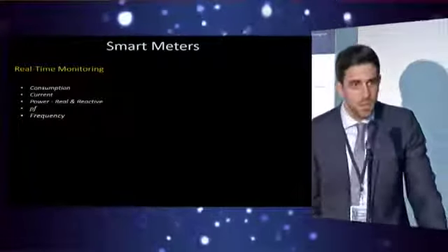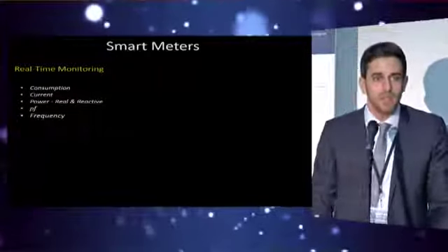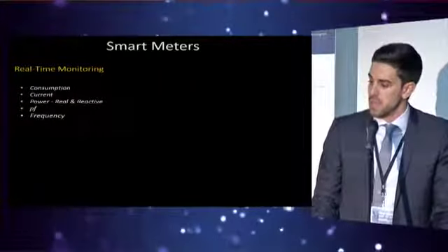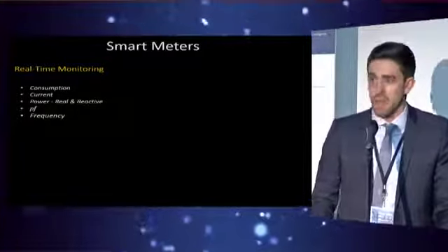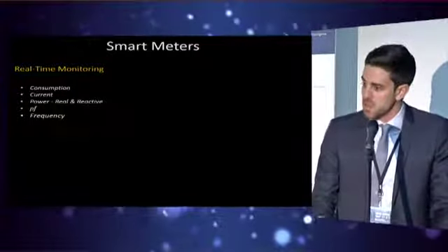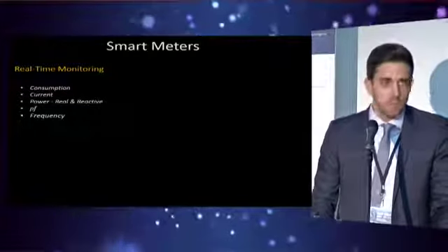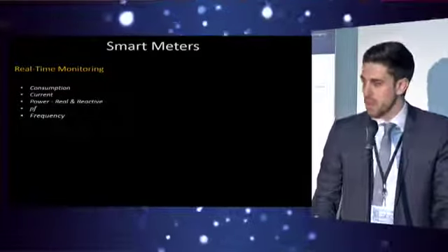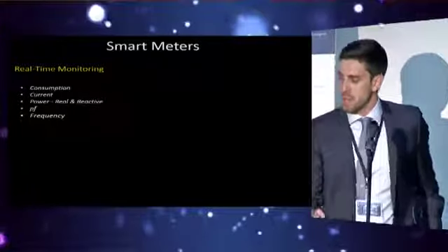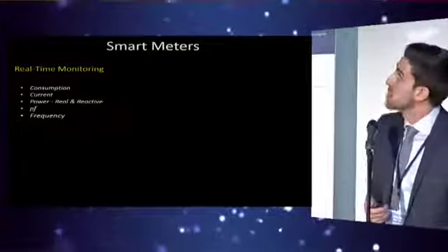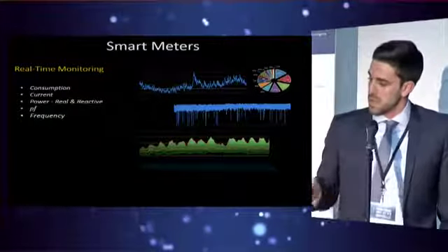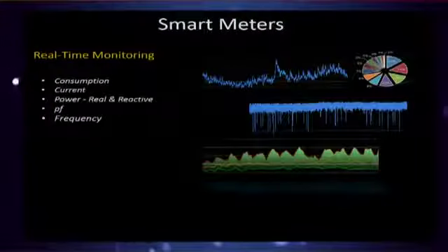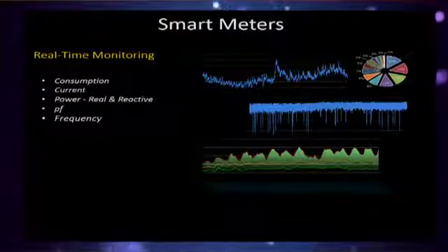Now, what are the smart meters used for? What was the reason behind this upgrade to the network? The smart meters give us the capability of monitoring in real time and remotely consumption levels, current per minute, power, reactive and real, as well as power factor and frequency, among other things. As you can see, these are graphs that display data minute by minute, any time during the day.